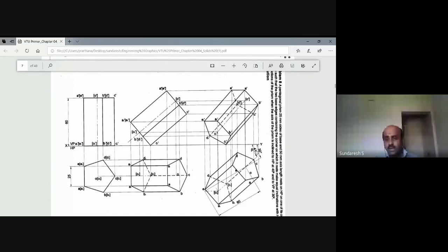Now this axis should be inclined to VP. In the sense, we are going to tilt the solid. The second position top view will be tilted in such a way that the axis O O1 is inclined to VP at 30 degrees. When you want to incline the solid so that the axis makes an angle of 30 degrees with respect to VP, then the concept of beta angle comes into the picture. This is where you should show the beta angle construction. So how do you do this?